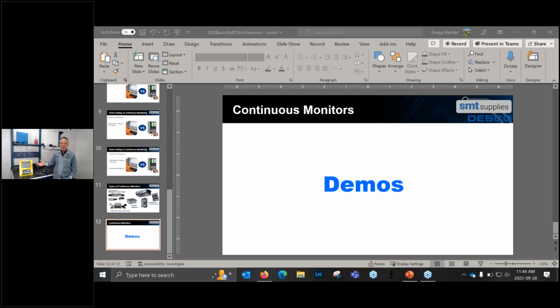So in our products, we have a tester that you can plug in, or a limit comparator, and it just makes sure, for instance, that the 10 meg ohm upper limit on the work surface mat meets what's in the monitor or what's on the tester. So that's really all you're doing. If you have a monitor that's out of spec, you may not be sure that you're actually failing low or failing high.